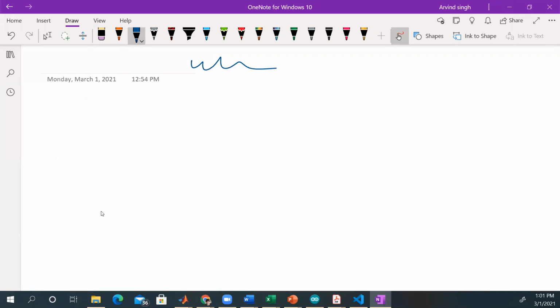So for DC motors, you will realize that the circuit is very simple. We always just have a source and a couple resistances. So we could start off here. The first thing you want to do all the time is just draw the type of motor that you have. So we have a shunt motor in this case. So we are going to have the terminals, our armature resistance, and the motor. And these things here represent the brushes, in case you're wondering why we draw that there.